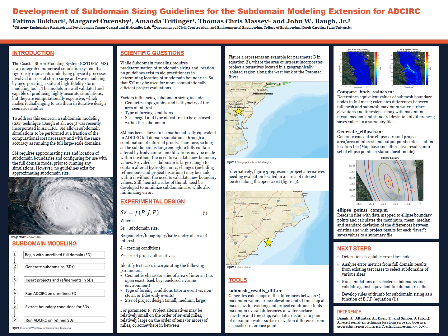So while subdomain modeling is a great tool that allows for multi-scenario simulations to be performed with less computational effort, guidelines for subdomain sizing do need to be developed so that subdomain size can be minimized while also minimizing computational cost. And in order to develop these guidelines, we need to consider what factors influence subdomain size, including geometry, topography, and bathymetry of the area of interest, the type of forcing conditions, and the characteristics of the